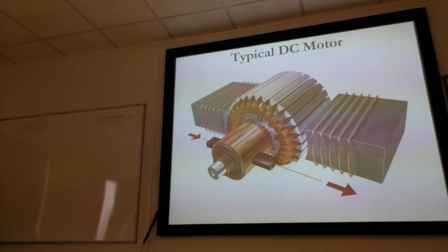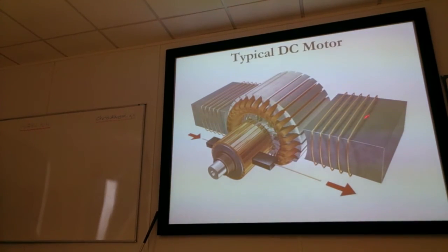Well, you can't, because you can't see where that's connected to. It depends. If the current comes in through here, then goes through the armature and to the other side, it would be series wound. If that comes in parallel with that current there, then it's a shunt wound motor.